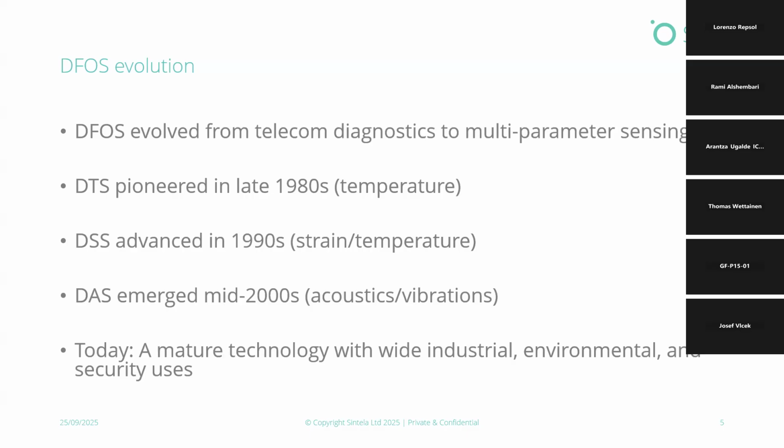Phase-sensitive OTDR-enabled DAS applications started to advance, and it converts standard telecom fiber optics into an array of geophones laid back to back every meter. So DAS performance is for tens of kilometers, for long distances of fiber. It's meter resolution. The strain resolution is quite high: picostrain sensitivity, and the bandwidth is tens of kilohertz. As I mentioned, from millihertz to over 50 kilohertz bandwidth that we can measure with that.